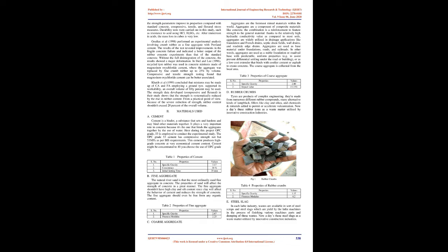Professor Subhathra Devi et al., 2014, conducted an experimental investigation on M20 concrete. On testing workability using a slump cone test, the workability of the concrete was found to decline gradually as the percentage of fine aggregate replacement increases. Concerning strength parameters, the author suggested that the compressive, tensile, and flexural strength parameters improve in proportion compared with standard concrete. Durability tests were carried out in this study, such as resistance to acid using HCl, H2SO4, etc. After immersion in acids, the mass loss in cubes is very low.